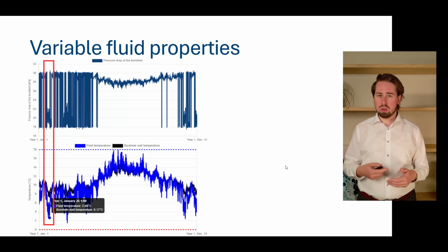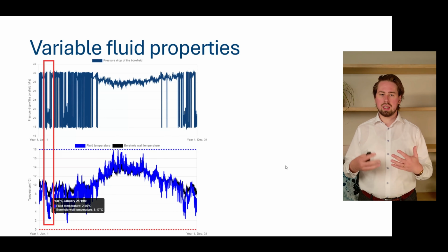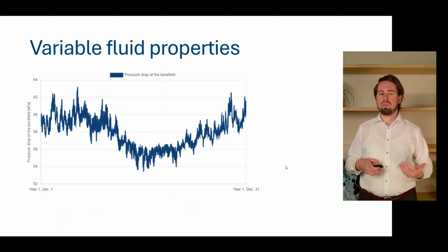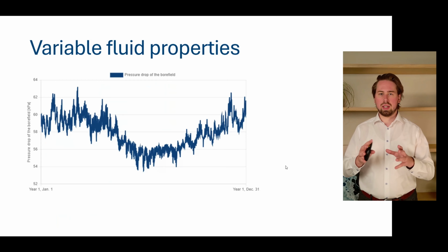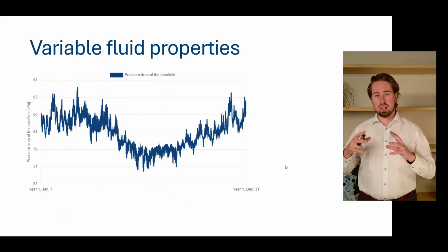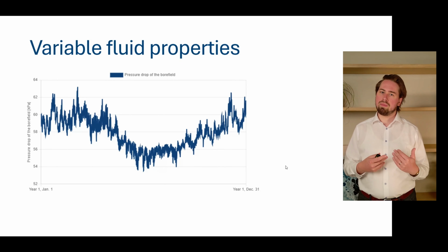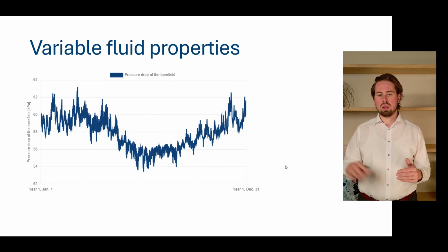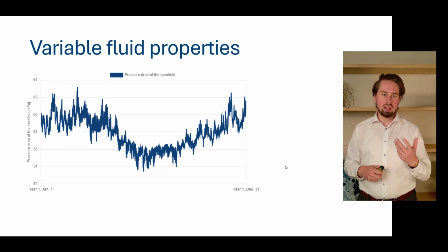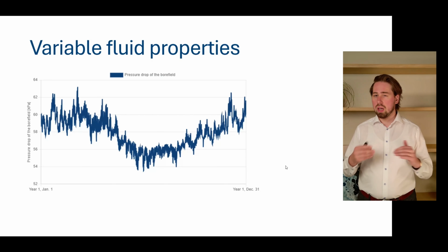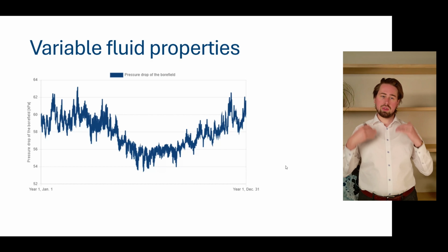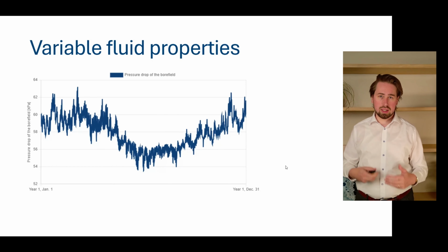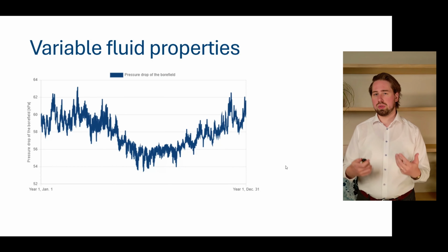To illustrate that somewhat further, we also simulated the same system now with twice the flow rate. Here you can see that we do not only have this continuous behavior in summer, but also in winter, meaning that the transition from laminar to turbulent is totally gone, and we have this smooth line. As you surely noticed, we're now not at the maximum of 30 kPa, but higher, because our flow rate has been increased, so our overall pressure drop is also higher, of course.